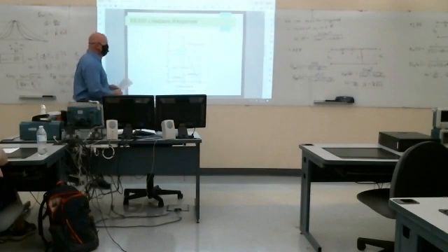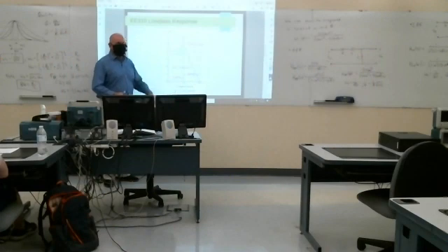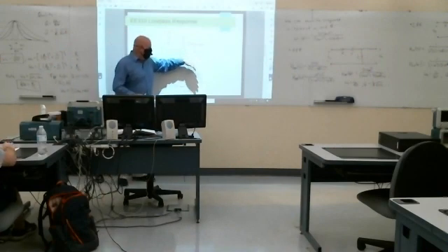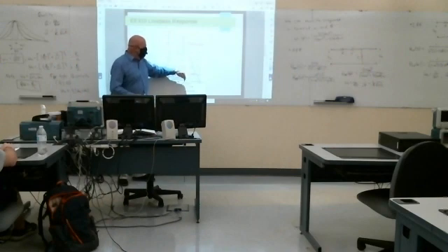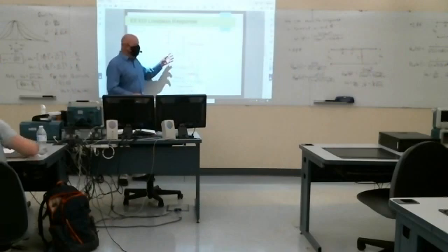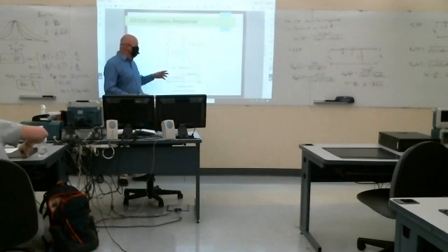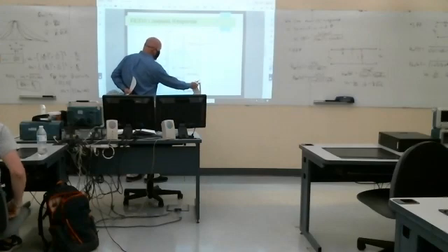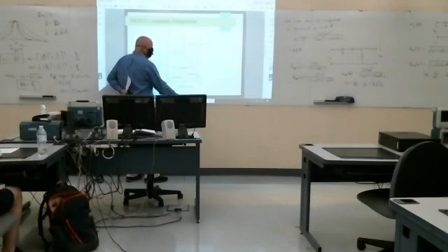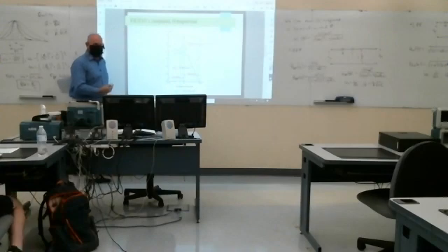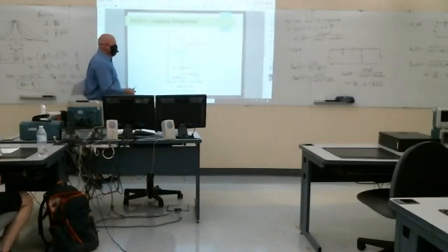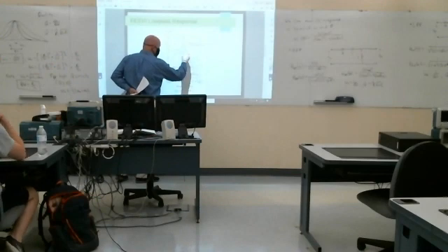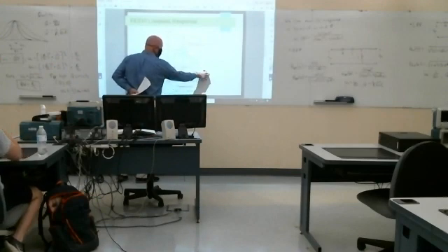So this is the corresponding low pass response with a cutoff at omega 0. Kind of looks like the mirror image of the high pass response. Again, on the edge, the response rolls off, and this is our Bode plot. So this is in dB. But if you'll notice here, as we go from omega 0 to 10 omega 0, there's a change of 40 dB, whereas with our first order circuits, we were seeing a change of 20 dB. So first order circuit would be like that.